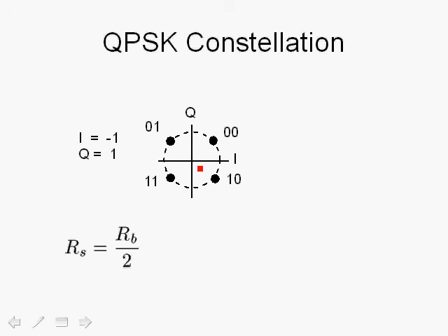You can also think of the in-phase axis as the real axis and the quadrature phase axis as the imaginary part. Within the two-dimensional space, we have points, in this case 4 points. Each point corresponds to a vector, and each vector represents a symbol. And each symbol has a coordinate, an in-phase term and a quadrature phase term.